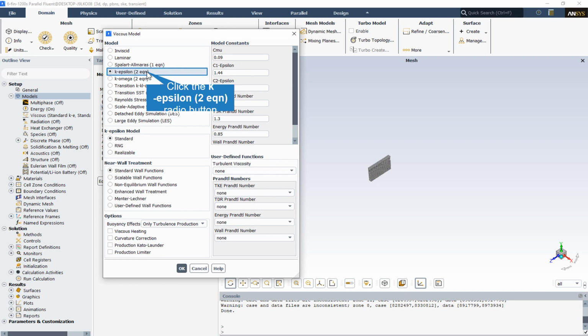That is a 2-equation turbulence model that allows the determination of both a turbulent length and time scale by solving 2 separate transport equations. The standard K-epsilon model in Ansys Fluent falls within this class of models and has become the workhorse of practical engineering flow calculations in the time since it was proposed.